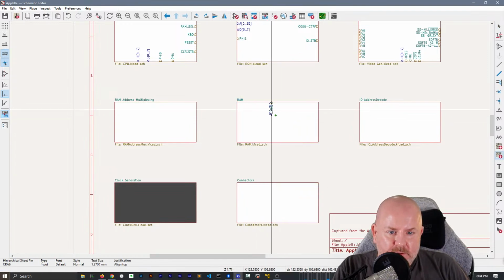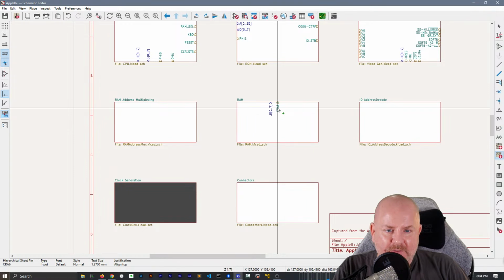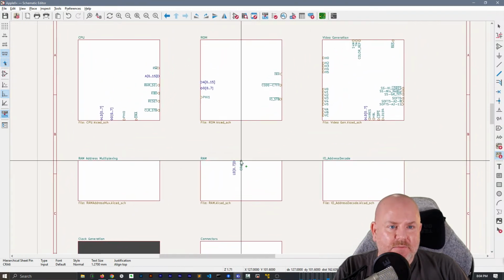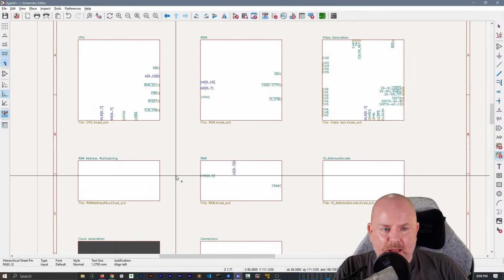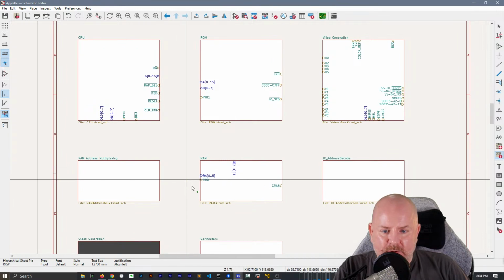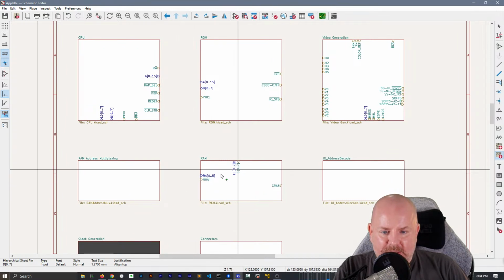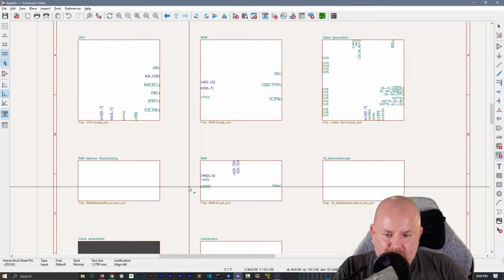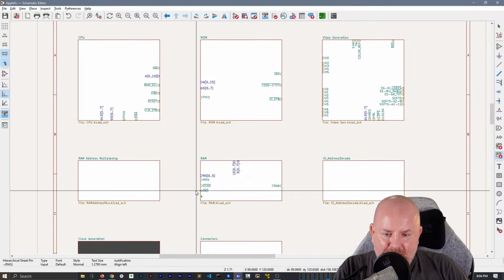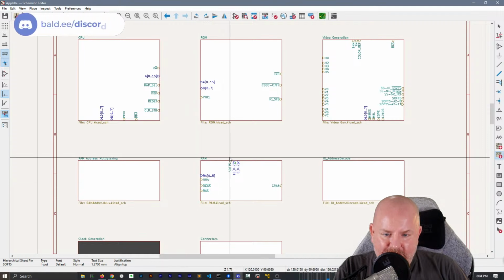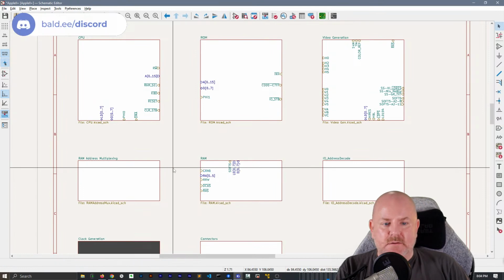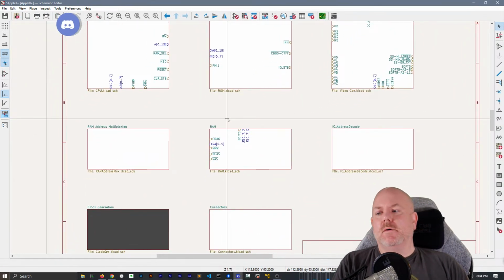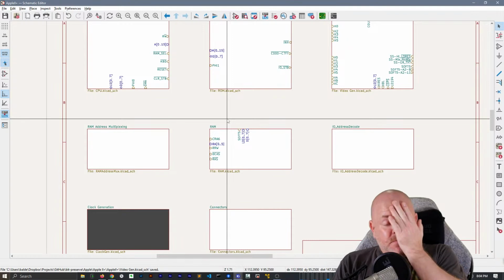So LD0CRA, I have no idea where that comes from. I swear I have not seen that yet. So that must be the IO decode side or RAM multiplexing. RAM addresses, maybe from over there. Read write, I bet is from over there. Data, it's got to be over there somewhere. What was this one? The DCA, RAS, Soft 5. I really need to figure out where that one's at. So, all right, cool. Well, that looks good.